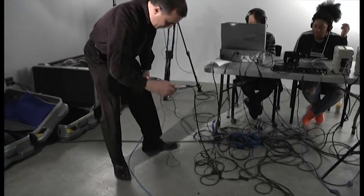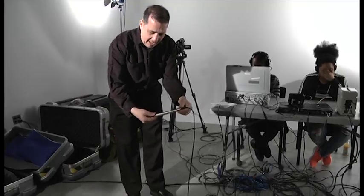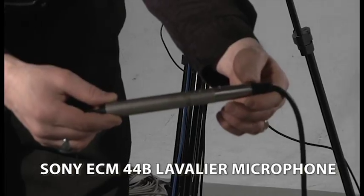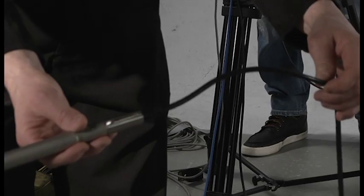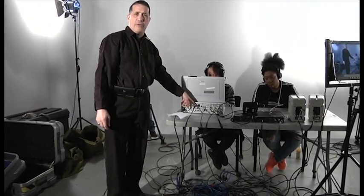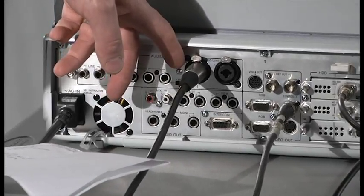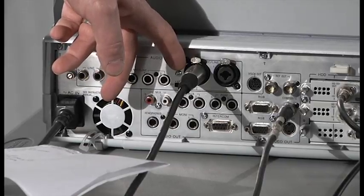So I dropped it out of my ankle, and it's actually on the floor. It is an actual physical ECM 44B style Sony lavalier microphone. It takes a battery. I've plugged it into an XLR cable, traced and then cabled directly into our Anycast's microphone or line XLR in. We've told the Anycast that this is a microphone port, not a line port. That's why it's receiving my microphone.